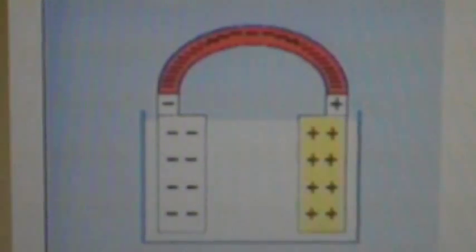The size and number of plates in each cell determines the battery's capacity. A motorcycle battery has either 3 or 6 cells. This battery has 6 cells that each produce approximately 2 volts. The cells are connected together in series, so the total voltage of the battery is about 12 volts. As the battery is used, the composition of its plates changes, and its acid content weakens to a point where the battery is discharged.